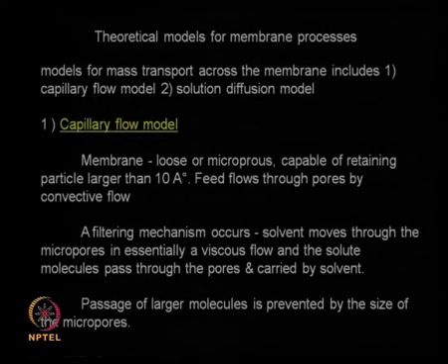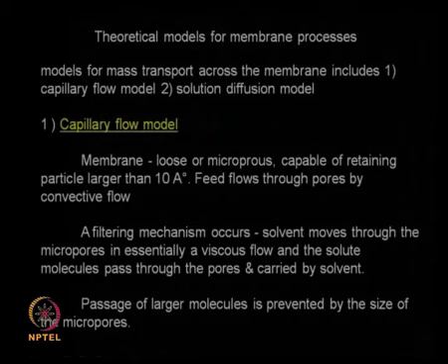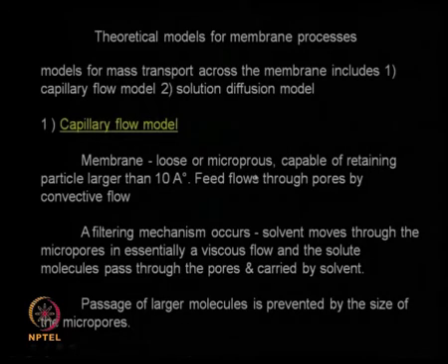Okay. There are several models available for studying the membrane process, but two important models I will discuss in a little more detail. One is called the capillary flow model and the other is the solution diffusion model. Most membrane processes could be clubbed under these concepts. Capillary flow, as the name implies, has a loose microporous material inside, and the liquid feed flows through these pores.